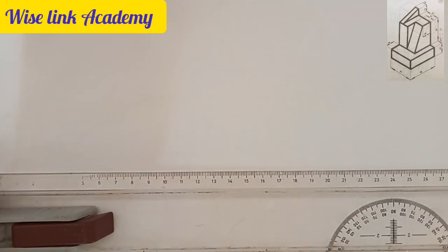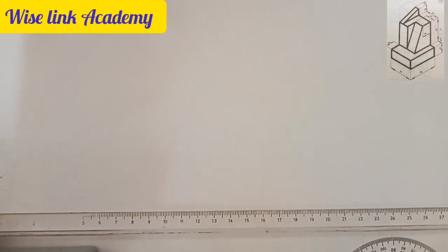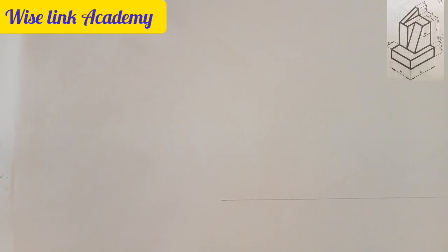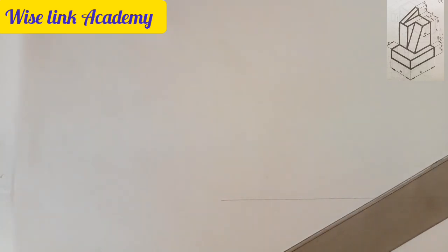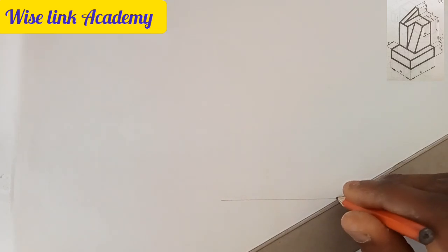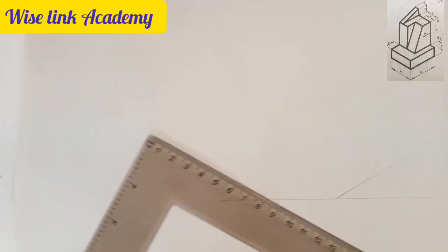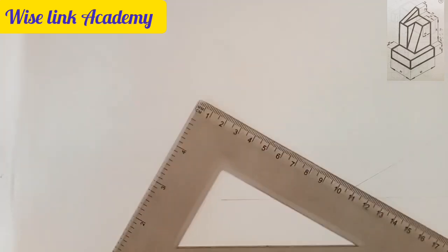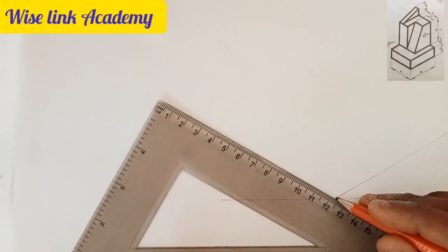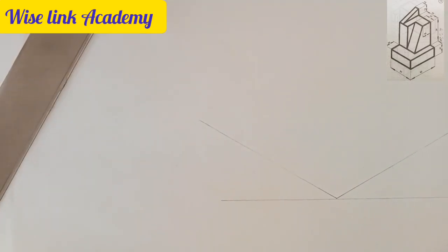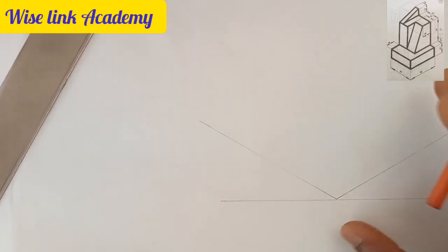Now this is my T-square, isn't it? So to draw my inclined line, draw a straight line first. You can see my straight line. After that, you take your set square like this. Project this upward like this. Turn it to the other side. Take it from here upward. You can see.